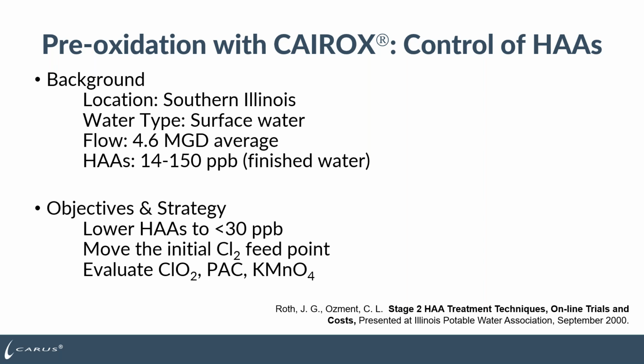So one of the things to keep in mind is that TOC, or total organic carbon number, it just depends on what makes up that TOC number, what specific type of organic is there. And then it depends when you chlorinate it. Sometimes you'll get THMs, sometimes you'll get HAAs, sometimes you might have issues with both. So in the case of this source water, HAAs were their concern.